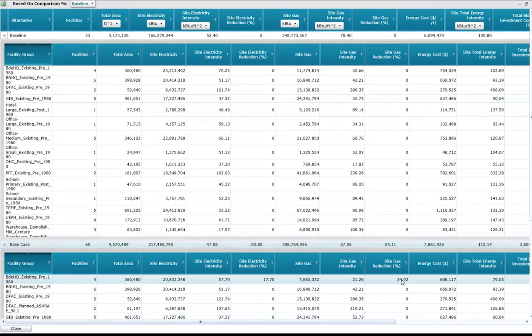There are some tweaks that we're trying to do with variable refrigerant volumes and some of the others. I'm going to say exotic today, and if I was back in the 1980s, I would have called the VAV exotic, right? So that term kind of moves with time and how long that technology's been in place and it's being used. Can we save more energy with VRF? Some cases, yes, and we're still evaluating the amount of refrigerant that's in the system and getting passed around, the complexity of the system, the maintenance of the system. I'm not here to proclaim one or the other. I'm just pointing these things out at this time.